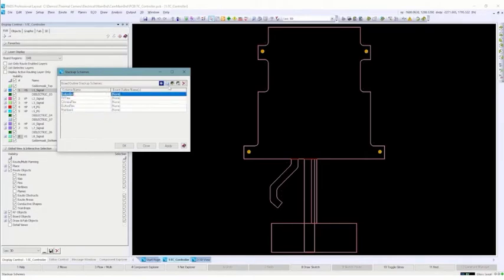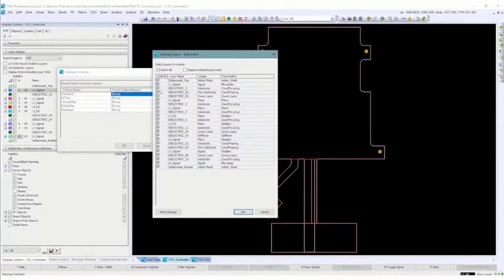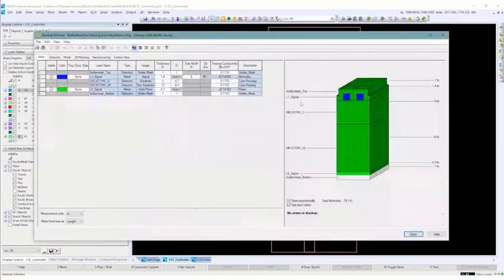So for our button board, we click on this, we can see all the layers that were just defined in our Stackup editor. So I'm going to include the solder mask. I'm then going to include my signal layer 1, my flex substrate. We'll also need our dielectric and then our layer 2 and then solder mask bottom because our button board's only going to be 2 layers. So if we do a stack up view of that, we can see what that looks like.